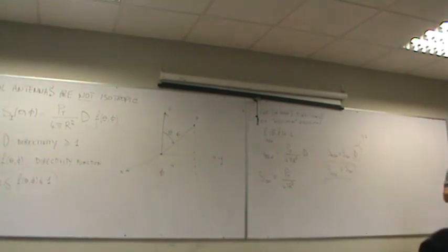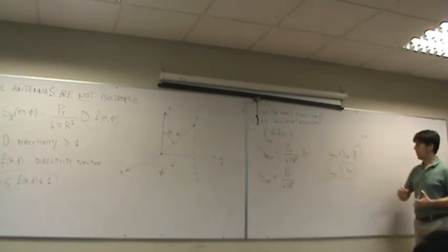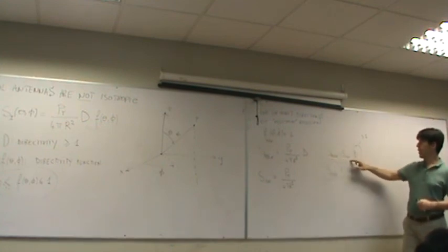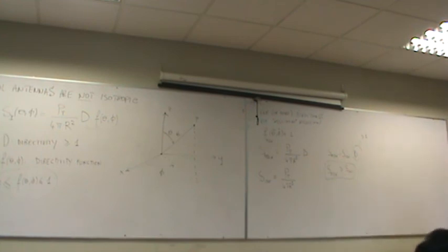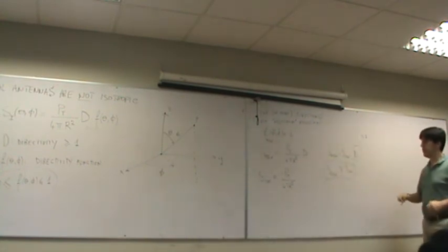You can, in principle, imagine that the narrower, the more concentrated is the radiation in a given direction, the larger will be the directivity. That is, the higher will be the power density with respect to the isotropic. Taking this into account, we will now derive a very important relation between those two parameters that is fundamental for the antenna theory.